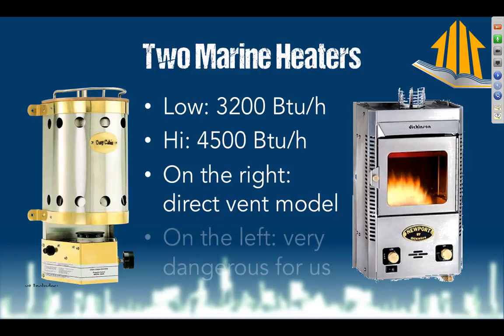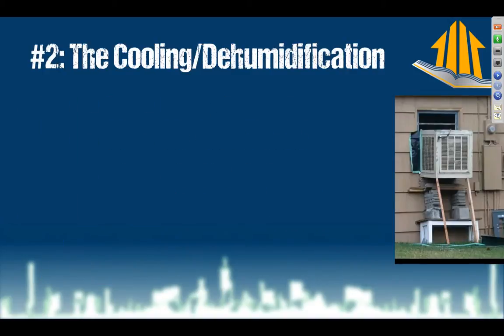and that is what I want, because on the left, that guy you can see at the bottom there, underneath the bottom of the canister looking thing, you can actually see the burner, and it's right out in the open. That means it's using air in the tiny house to burn with and then sending it up the chimney. And my tiny house, as you remember from last week, is super, super tight. So there's no possible way this thing is ever going to work. I'm going to have to replace it immediately because it's just going to keep on shutting off.